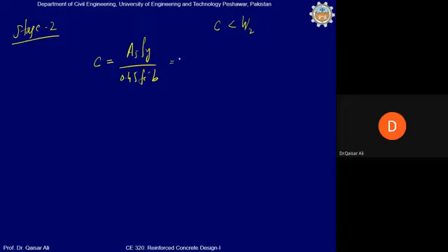So you know all these values. As is 1.32, Fy is 60, divided by 0.45 multiplied by 3, and b is 12 inches. So give me the value. Quickly. 4.88 inches.